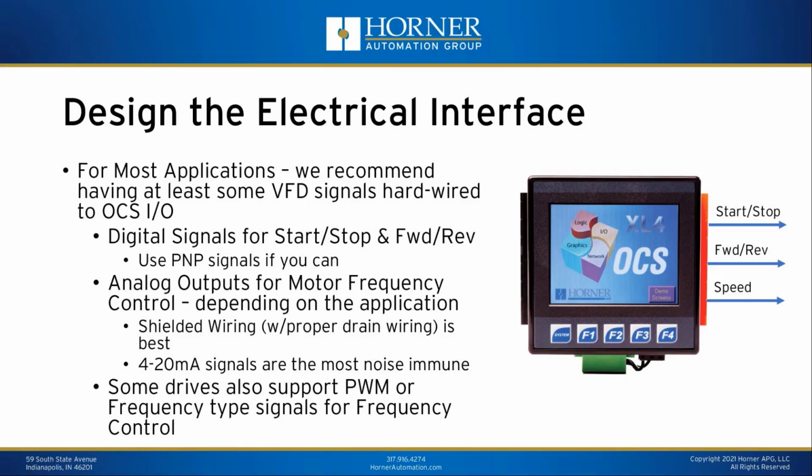But in most applications, especially relatively small ones, it's usually a good idea to have some hardwired I/O for things like starting and stopping, changing direction, adjusting speed. Sometimes it's just more convenient. You know that regardless of the communication status, you're going to be able to start, stop, change speed, whatever the case may be, at least have basic control functionality. Okay, so that's a recommendation we typically use.